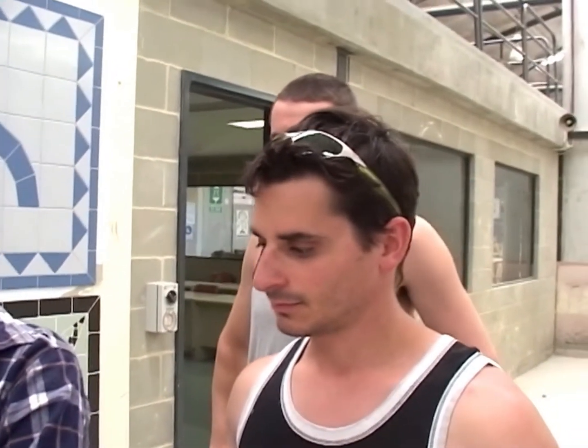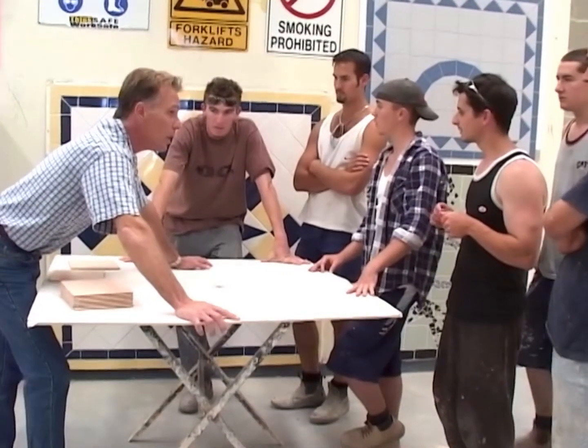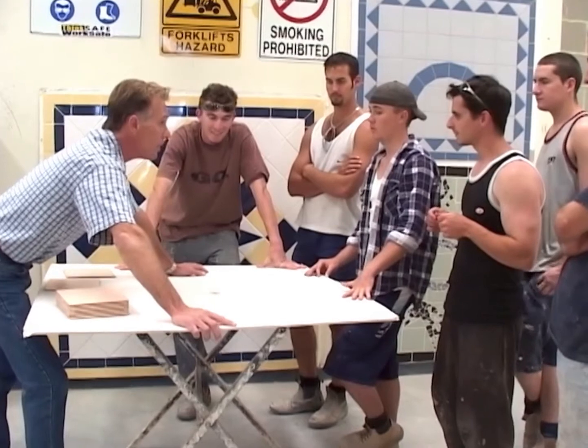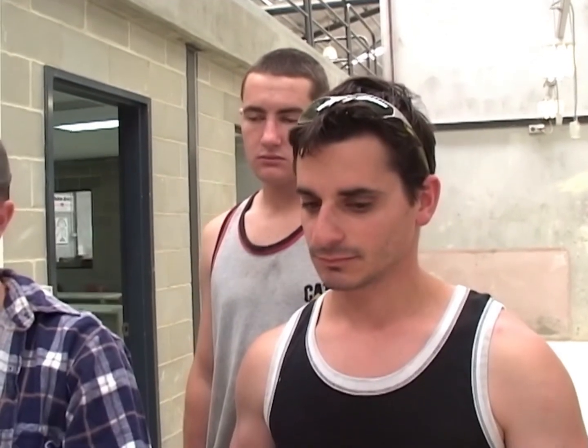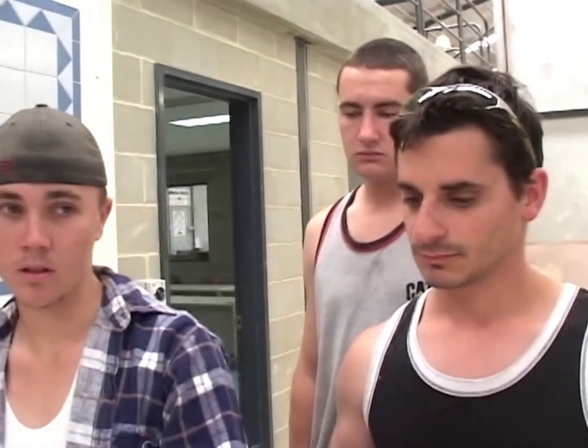Does anyone remember the circumference that we came up with this morning of this outer circle? 720. 720, that was our diameter, yes, that's right. But we multiplied it by pi, 720 by 3.14. 2265. That's it. So we were well and truly over 2 metres as a circumference. So if you lay this line out, from there we divided that by 4 to simply give us our quadrant, which is 1/4 of a circle, or 12 o'clock to 3 o'clock.